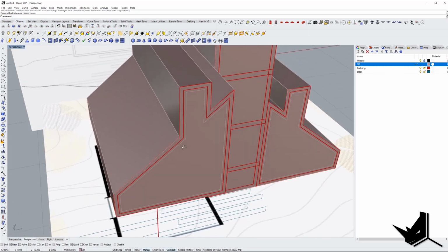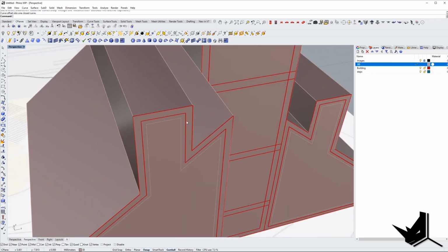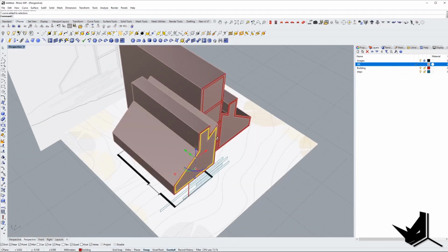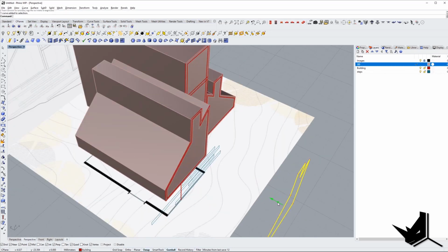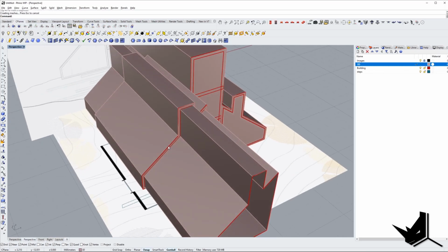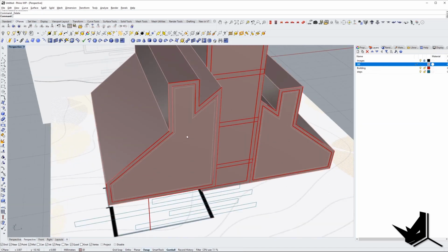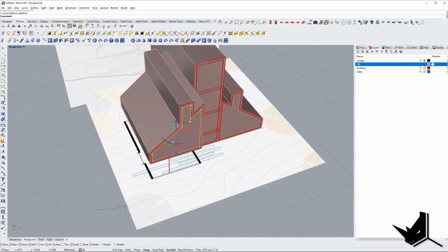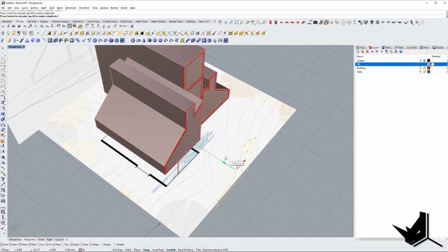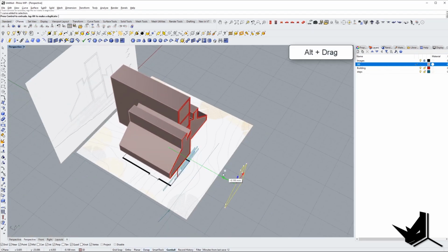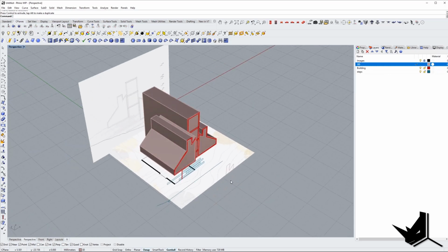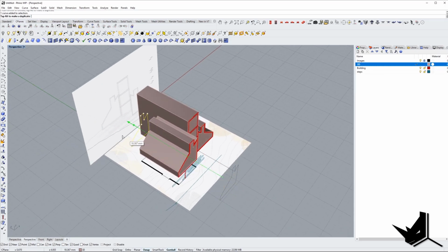And here, what I want to do, I want to actually split this element. So I'm going to use this curve. I'm going to copy it over, and I'm going to create one extrusion from it. And I'm going to say Boolean split. I'm going to split this guy. So now we have two inside, and then one more time, I'm going to do the same thing here with this line. I'm going to take this line, the most inset line, and I'm going to extrude it as well.